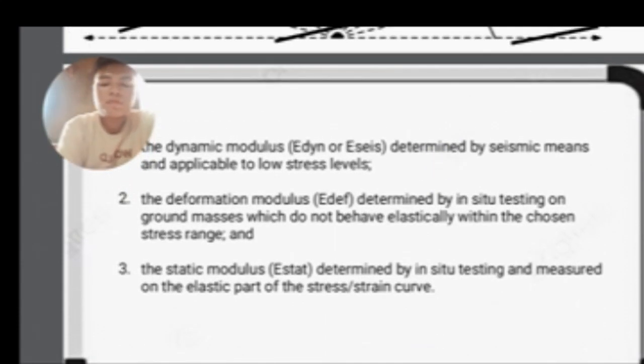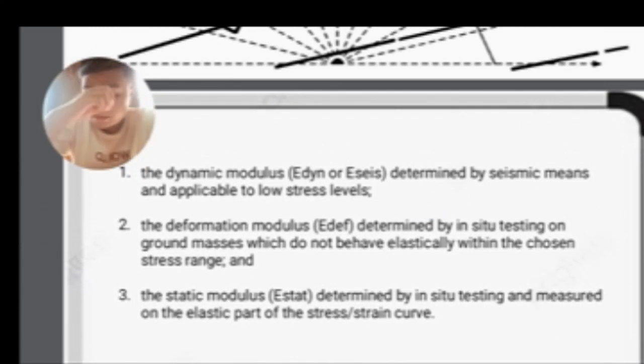The intensity of load imposed by the seismic wave is small, causing very much smaller strains than those imposed by a large field test, and also by the proposed construction, which are sufficient to cause large strains. The seismic wave acts for a very short time on the mass, while the load used to measure the static modulus is by comparison applied over a long period of time. It is now well recognized in continuum mechanics that shear modulus decreases as shear strain increases.